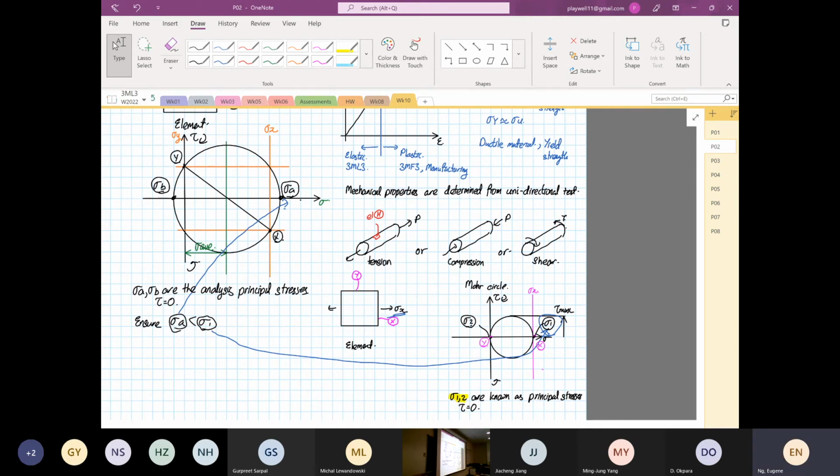This table over here, if you look at this table, where is it going to fail? Is it going to fail at the center? The answer is no. It's going to fail at the joint. No point calculating stresses that are not the maximum. You have to calculate stresses where it's the maximum. All we teach now is we give you the structure, find element H, find element K. What if the question doesn't ask you to find element H and K? You find where they are. So now we are still teaching. Later on is where you guess where the failure is.